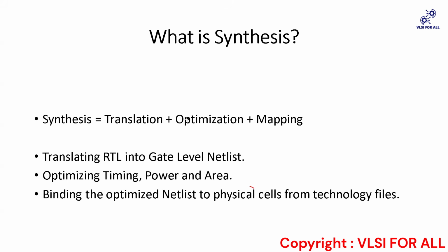So let's go to the other optimization technique, which is ungrouping. Ungrouping basically merges the subdesigns of a given level into one parent cell or design, you can say. It removes hierarchical boundaries and allows the levels of logic to be reduced and improves area by sharing logic. So it basically merges subdesigns into a parent cell. It removes hierarchical boundaries and allows our DC compiler to improve timing by reducing the levels of logic and to improve area.